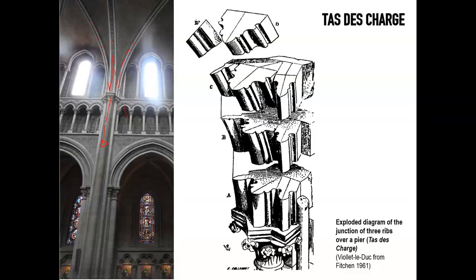Now this is obviously the architectural effect, but the means through which this happens is a very thorough control of masonry skills that inevitably have to convey forces in very concentrated spots. So a critical point that normally has to be addressed in any of these buildings is the springing point, where the transverse ribs, like this one here, and the diagonal ribs and also the side ribs sometimes, they all converge together.